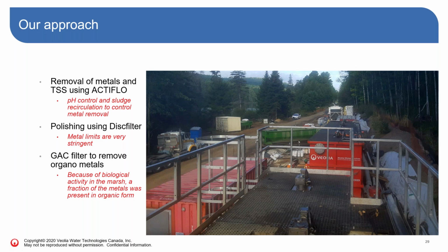The approach in this case is, again, removal of metal and TSS using active flow. So again, pH control, sludge circulation to control metal removal, polishing using this filter. That project has very stringent metal limits also. And we had a GAC filter actually to remove organometals.